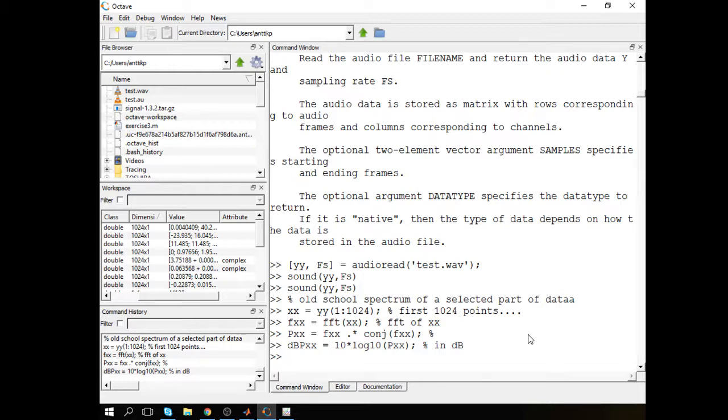If you want to calculate the real frequencies, you have data from 0 to 1023, 0 is the first frequency, so offset by that one, divided by 1024, multiplied by sample rate.